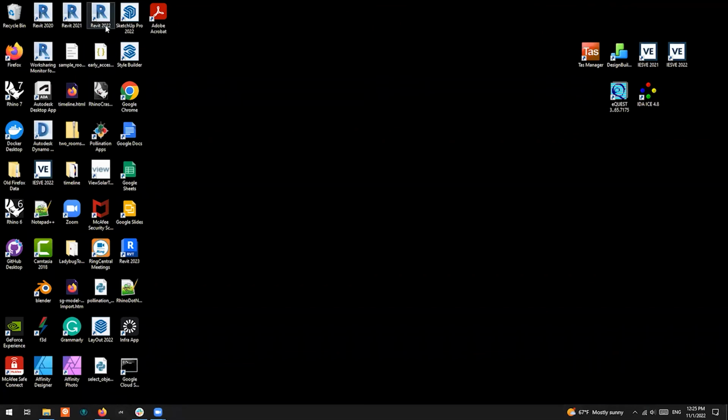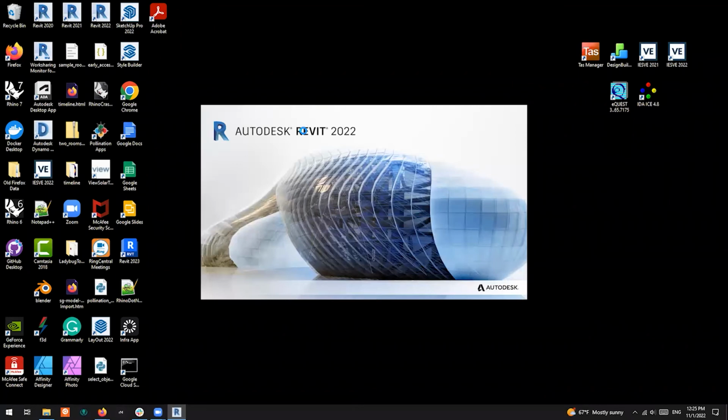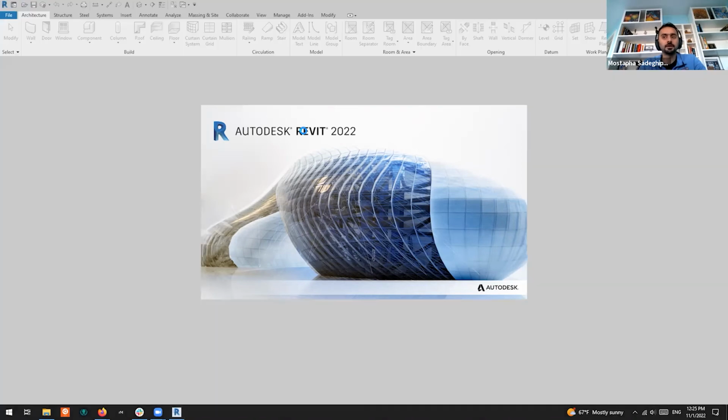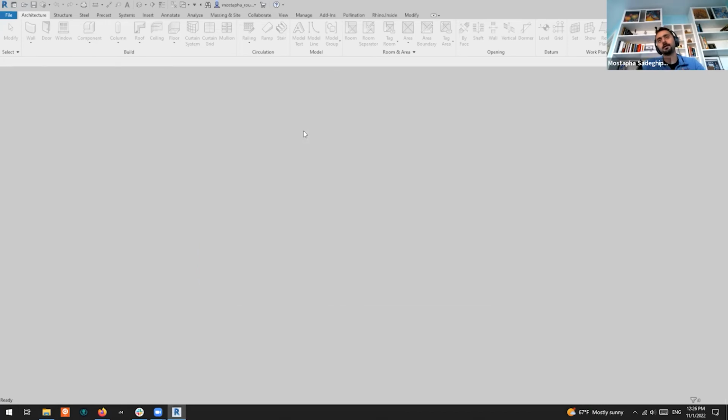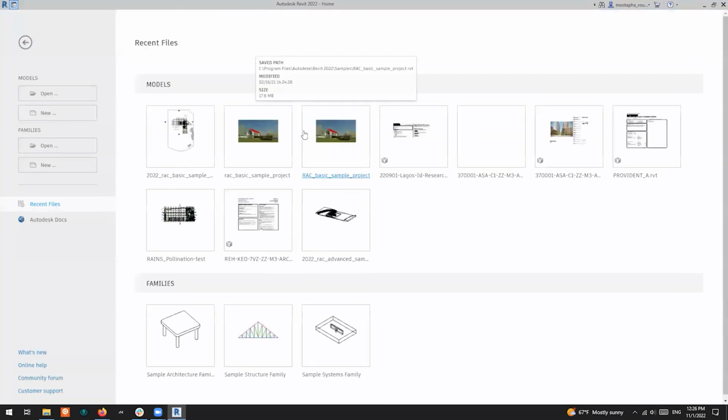Well, I was just trying this on the fly. I'm getting an error that says I can't find any rooms or spaces that pass the specified filters. Because your link, did you do the thing that I said, to open it as central and then save them? Oh, I didn't process it like that yet. Yeah, maybe that's why. I have to have a central. I have to do the processing. You have to set it up correctly.